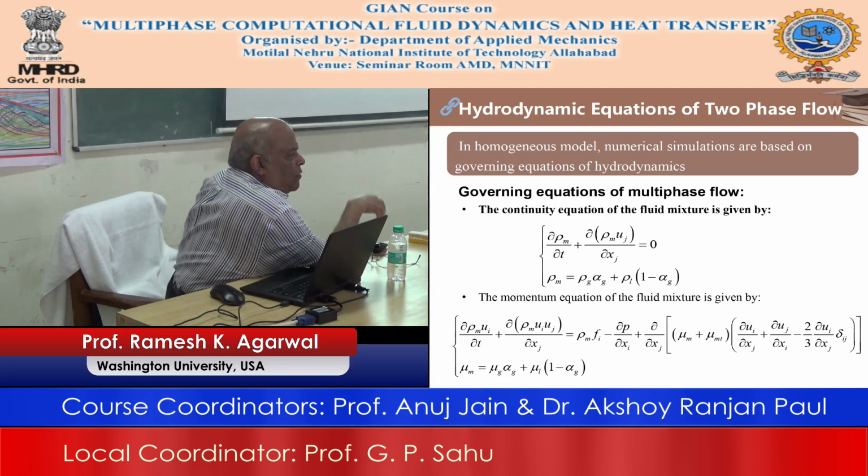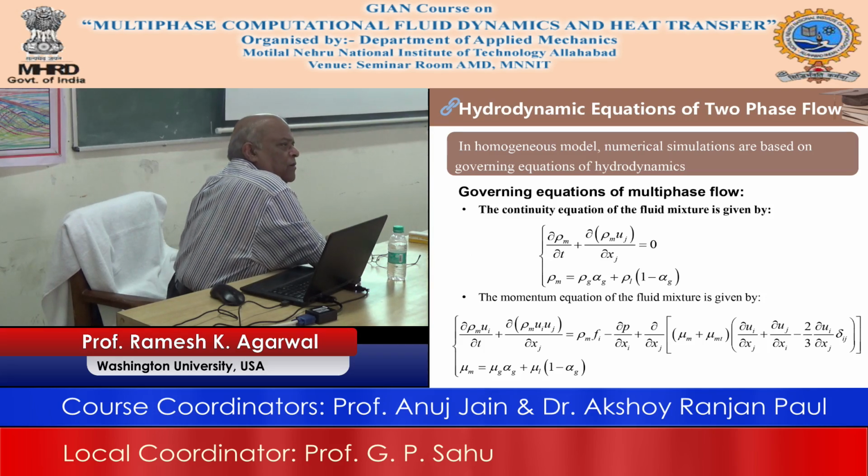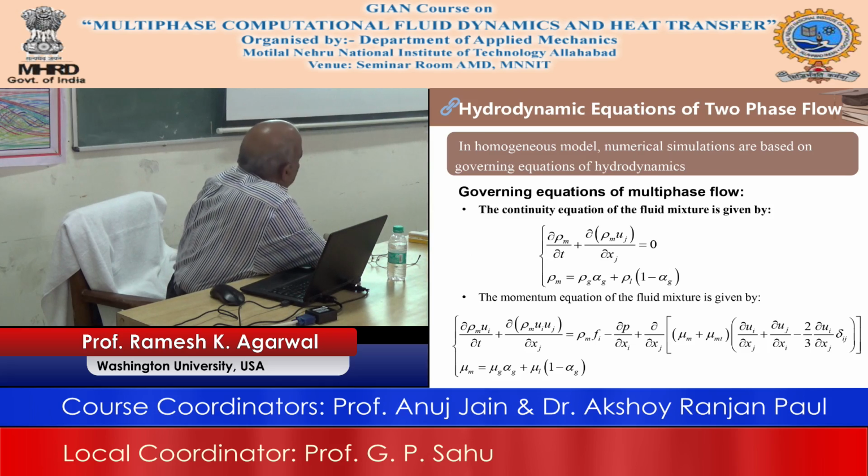But conceptually, the way we are calculating density is the gas density times alpha G plus the liquid density times alpha L, where alpha L is replaced by 1 minus alpha G, because alpha L plus alpha G must be equal to 1. This is the momentum equation, which is standard, and here you have again, just like we did for a nanofluid, the viscosity of the mixture.